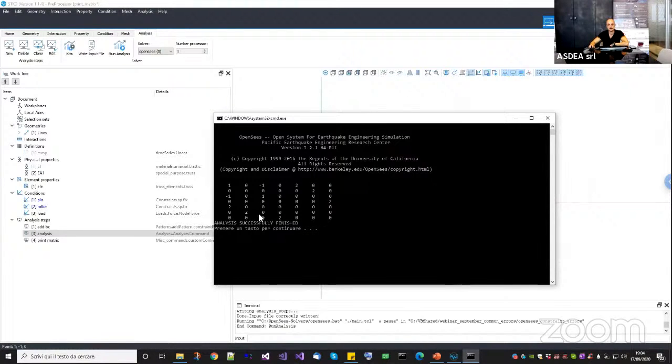Then I don't have a third column with a number here because the x of the second node is free, while the y displacement of the second node is fixed. So once again, I have a constraint handler here, okay? So this one is fixing what? The y displacement, and you see it from the column of the second node. Now, as you can see here, you see those 2, just because I've chosen 2 on my user interface there.